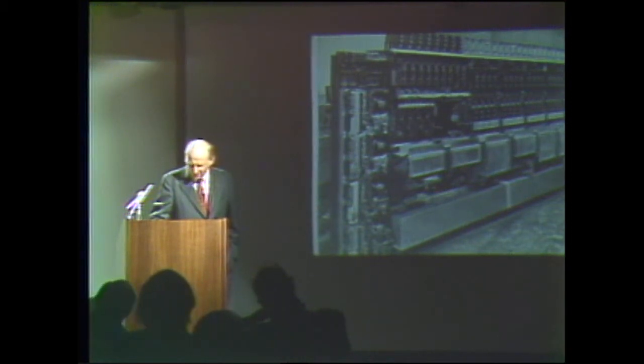In some sense, the Selectron can be viewed in modern parlance as an integrated vacuum technology. And I'll say that we thought of many other integrated vacuum technologies. For example, we thought of a completely binary unit that would multiply and add, that was also built completely by means of secondary emission stunts with many floating electrodes that influence one another.